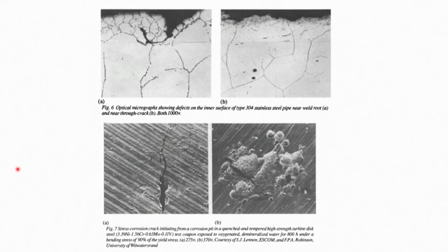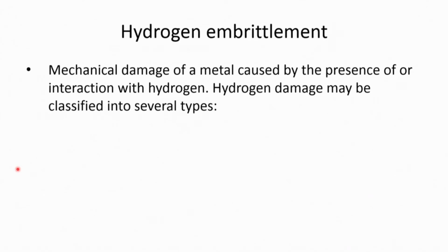So, if you quickly go through the stress corrosion cracking problem and think of its mitigation, the best way to minimize the probability of stress corrosion cracking is by choosing a proper material for the proper environment. The second way to get rid of this problem is by reducing the stress level of the material, particularly the internal stress present in the component, and of course, by the application of inhibitors you can reduce the aggressiveness of the environment. By the application of cathodic protection you can also reduce the stress corrosion cracking tendency to a large extent.